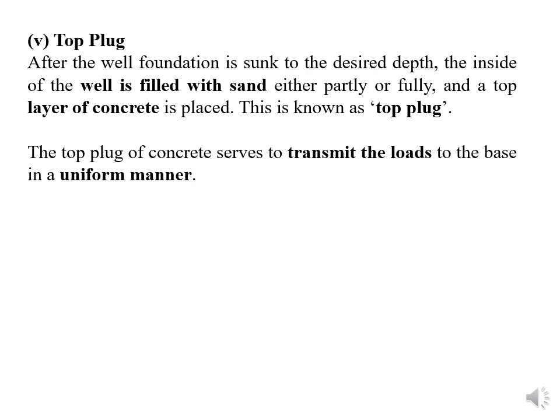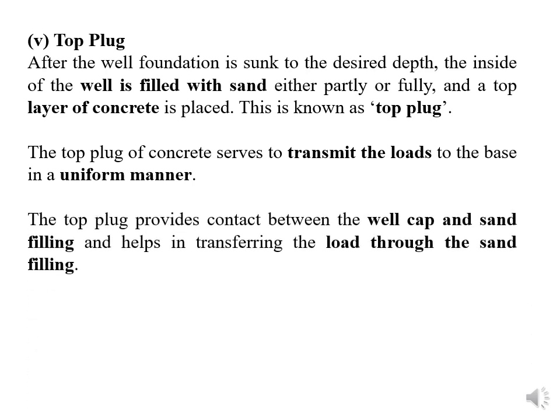And definitely the sand should be compacted inside the well in a proper way. The top plug provides contact between the well cap and the sand filling. As you know, above the top plug we can construct the well cap. So in between the well cap and the sand filling, it helps in transferring the load through the sand filling.